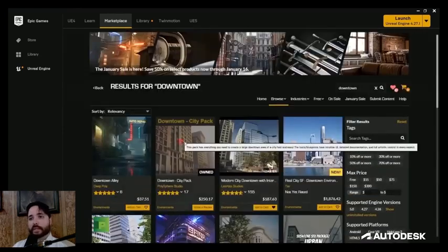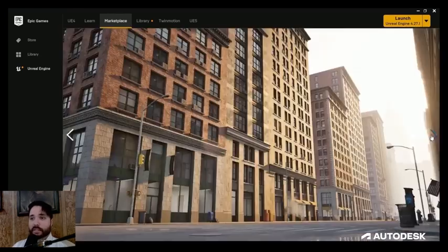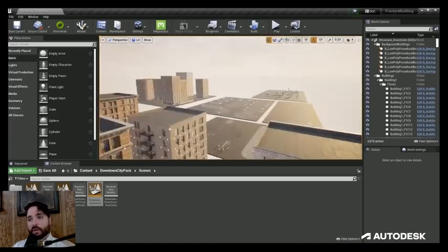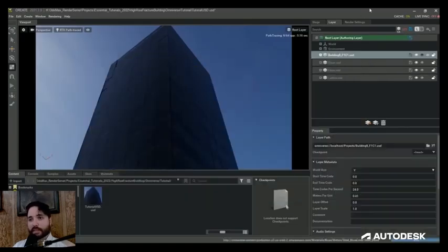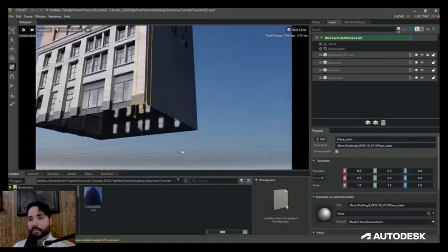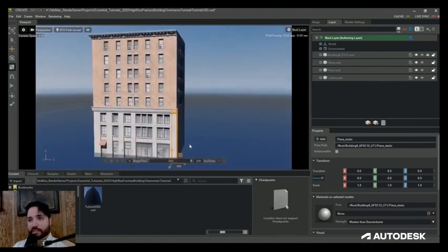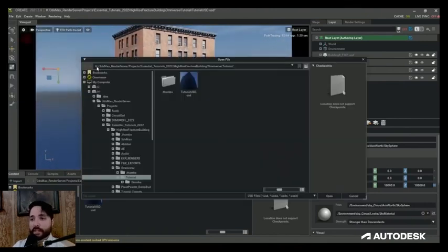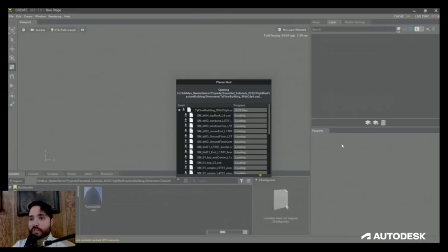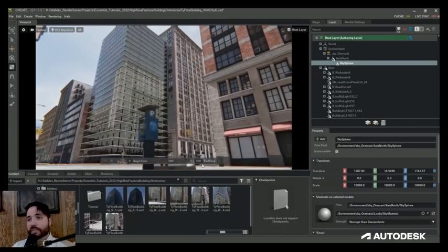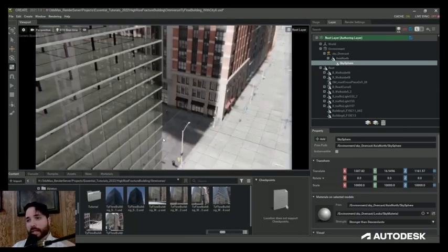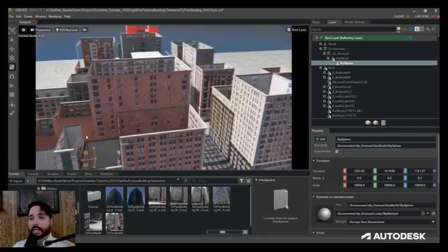Exporting these building assets was very easy. By using the Unreal Engine connector, all I had to do was right-click on an asset and then click Export to Omniverse. And then all of the shaders and the materials were brought in and were ready to use. So jumping into my project file now in Omniverse, you can see all of the building textures, the lighting, and the post-production settings are working in real time.